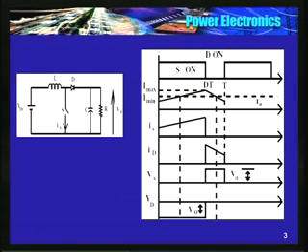So when I close the switch, this jumps to the current that is flowing through the inductor or through diode D, and increases linearly. When I open the switch, it becomes 0. Immediately the current that was flowing through S just prior to opening it starts flowing through the diode. So this is the diode current.